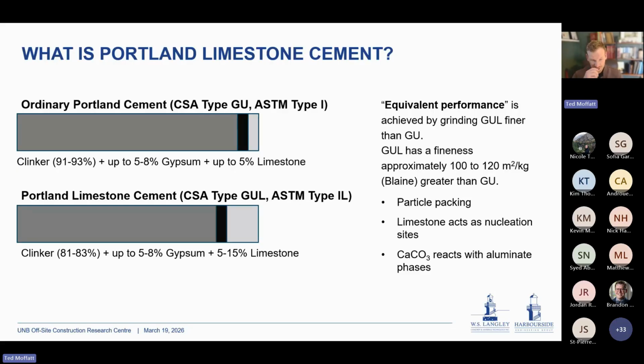So you take those ingredients and feed them into a rotary kiln that's heated to 1450 degrees Celsius. What comes out is clinker, which is about the size of a golf ball. You crush that up and blend it with gypsum. Gypsum is needed to keep your clinker from flash setting. If you didn't have gypsum in there and you added water to it, your powder would flash set.